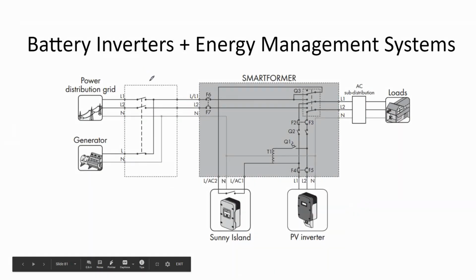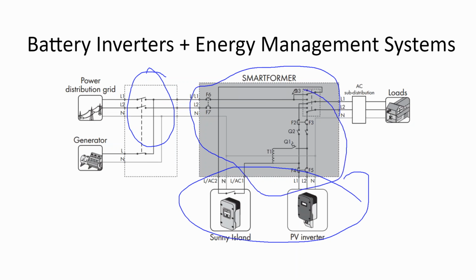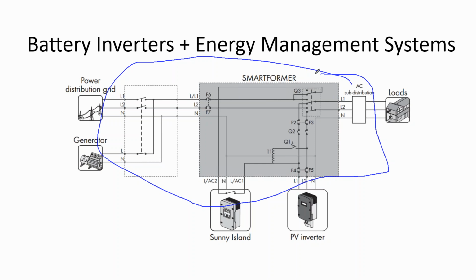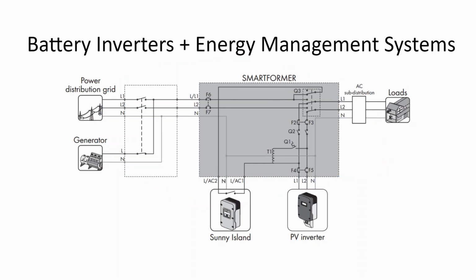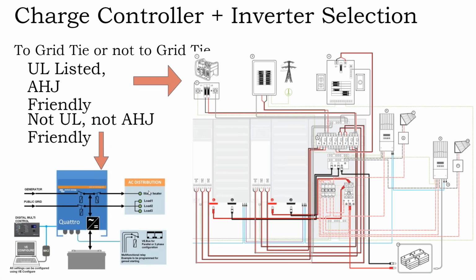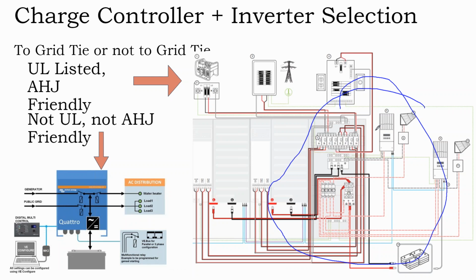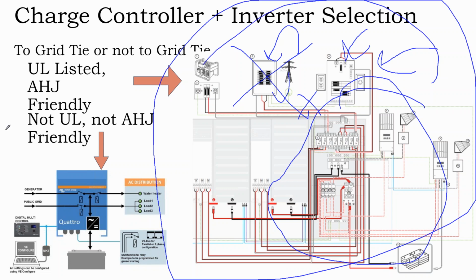How that actually plays out is you have to have a disconnect between the grid and your battery system, and maybe some automatic transfer switches and some relays and some transformers, a lot more interconnection gear in order to isolate the system from the grid if it's grid tied. So basically, to run a house off grid when it's a grid tied system, not just do you have to have a battery as well, but you have to have this complicated interconnection equipment. Maybe we'll have part of our service panel grid tied, and then we'll have a separate service panel that's isolated. And so we'll have a transfer switch, and then the grid side component will go down and the protected side will go up. But all of this stuff costs a lot of money.